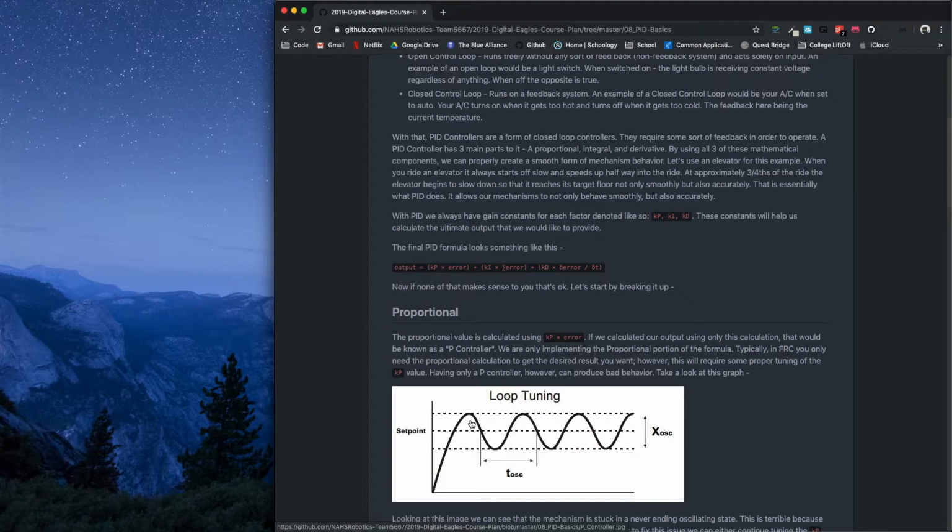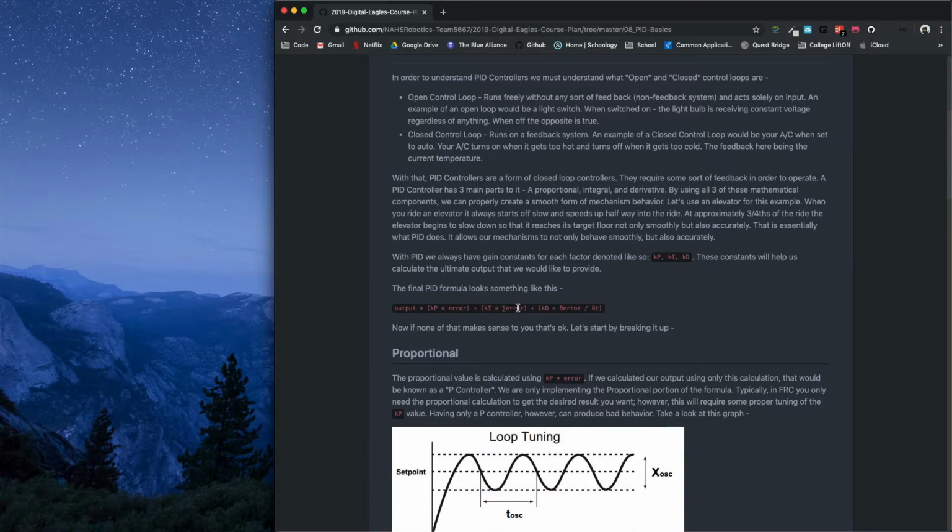And essentially this helps us, it basically tells the PID controller how much it needs to account for to get to where it wants to be. And so that's what an integral essentially is, just the area under the curve, and it helps us get to where we want to be. Then it's multiplied by the integral constant, and then we have the derivative, right? So the change in error over the change in time, multiplied by the derivative constant.